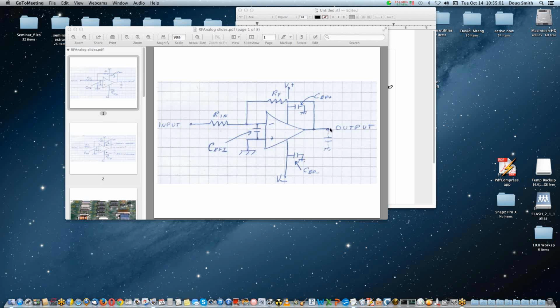And then look on the output with the scope both for low frequency AC and DC offset, and feed it a controlled amount of RF through the same value resistor you're going to use in your circuit. And this is all nice on it looks like an RF circuit over a ground plane. It looks like you built a little microwave amplifier, so that's what this thing's going to look like. And that's the only way I know you could actually tell for sure that it's going to work in your circuit with the given RF excitation.